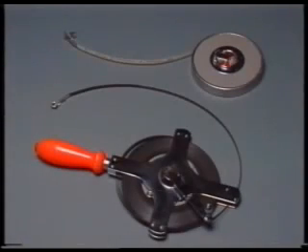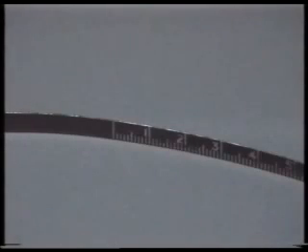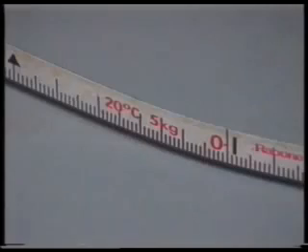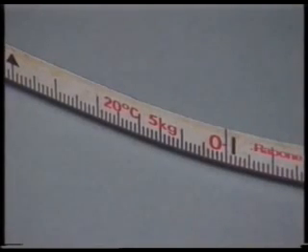If high accuracy is required, steel tapes should always be used, but they must be handled carefully since they will form kinks and can easily break if trodden on or if a vehicle runs over them. Steel tapes are normally graduated every millimeter, and they carry details of their standard temperature and tension. Be careful when taking measurements with them. The zero point is not always right at the end of the tape.